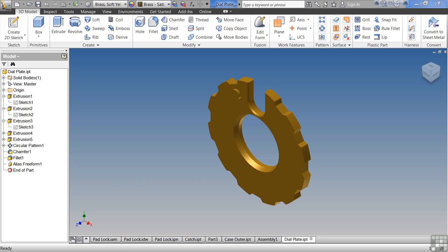Inventor is a parametric modeler. It creates parametric part models. You can create and edit 3D geometry efficiently with parametric part models, which are controlled primarily by geometric and dimensional constraints. A typical part consists of 2D sketches with geometric and dimensional constraints and gives you the resulting 3D solids that you see on the screen.